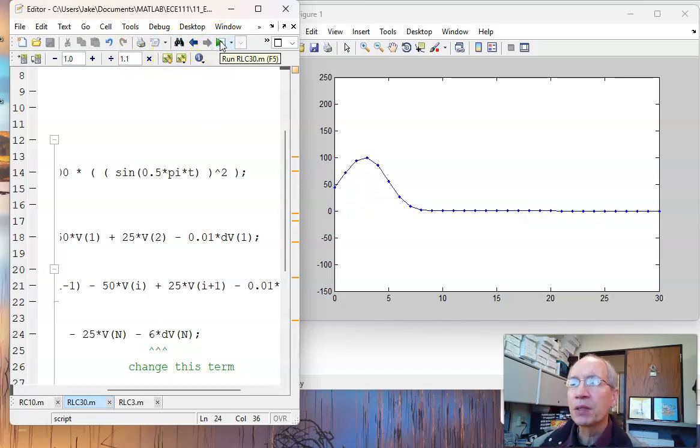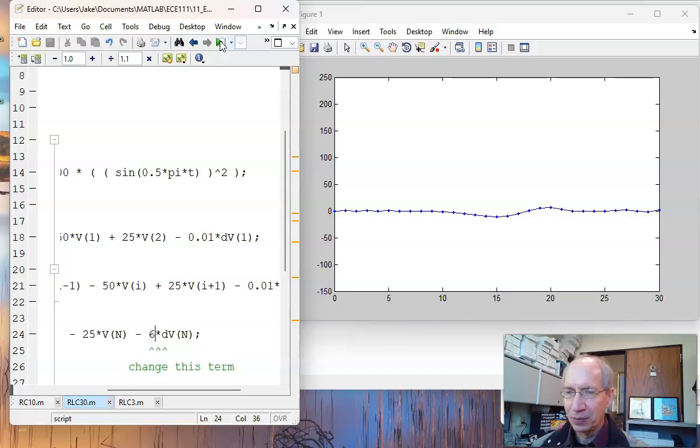There is a theoretical number that you need. From a practical standpoint, you don't have to be dead on. If instead of absorbing 100% of the energy, I just absorb 90%, that's still pretty good. And that looks about right. So say I want 1 over RC to be 6. That gets rid of most of the reflections.